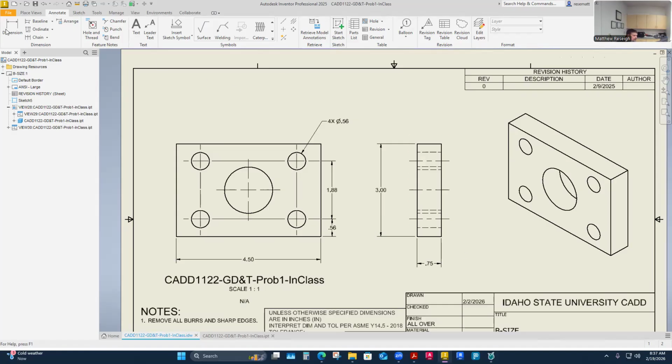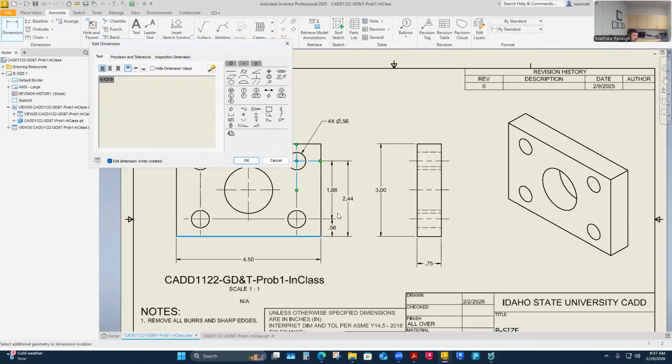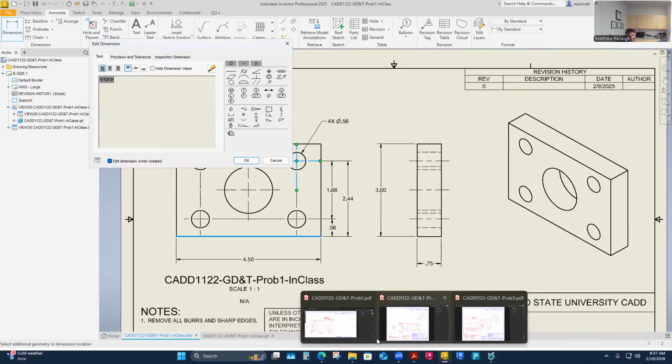And the other option I would have is that GD&T will still allow you to do a baseline dimension, which would be this dimension for that next feature, like this. You would see me do more of this in AutoCAD. I would kind of avoid this only because we weren't doing any GD&T, and my drawings had a tolerance applied to them because we have a tolerance block, which we're going to dive into the weeds on today too. So there was a tolerance applied, and chain dimensioning with a tolerance applied is where you can get tolerance stack up. If one is off, even within its own tolerance, it'll affect the other's position based off its tolerance.